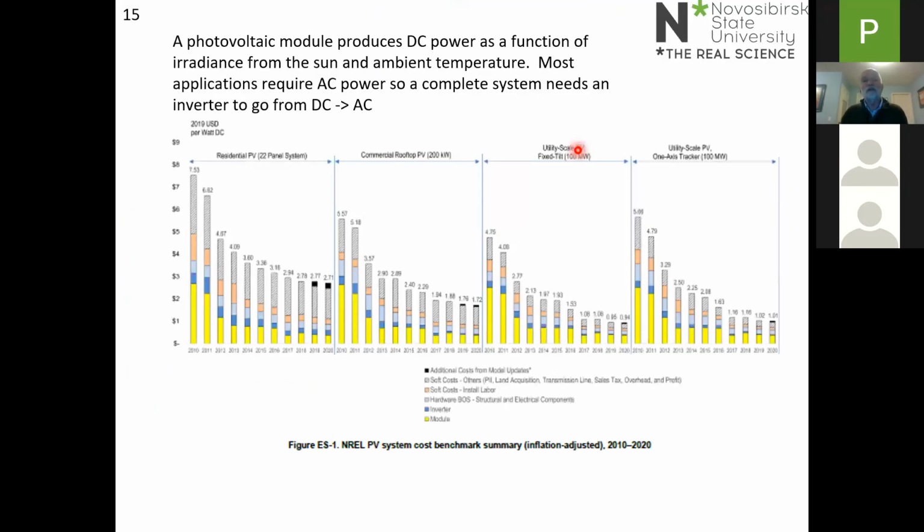Okay, one of the interesting things about photovoltaics is that it has less change of cost with scale of any of the renewable technologies. If you take a large wind turbine, say a 2 megawatt wind turbine, I told you before that will cost you about $1,000 per kilowatt. If you want a very small wind turbine, say a 5 kilowatt wind turbine, you'll be paying much more per unit power than that price would indicate.